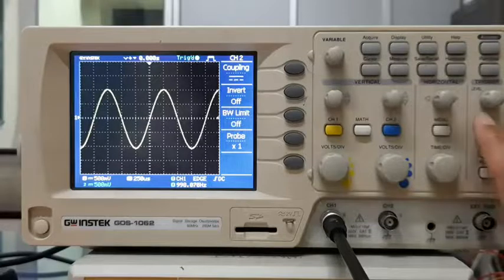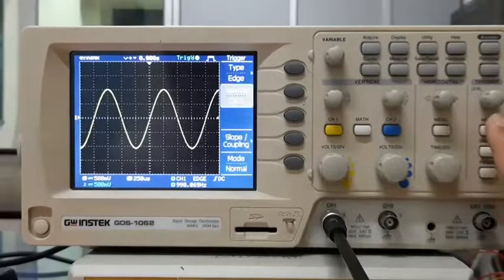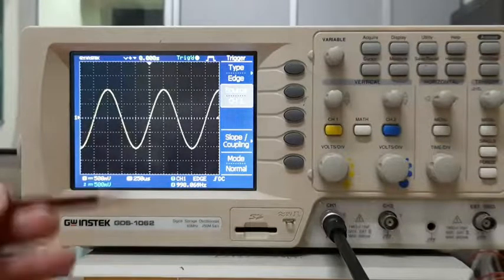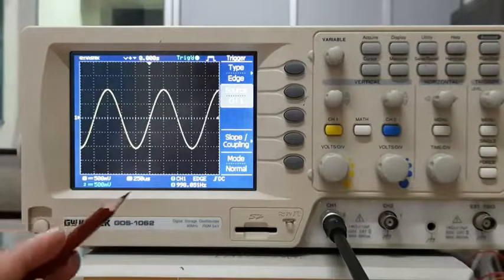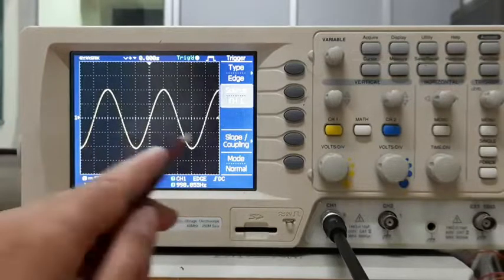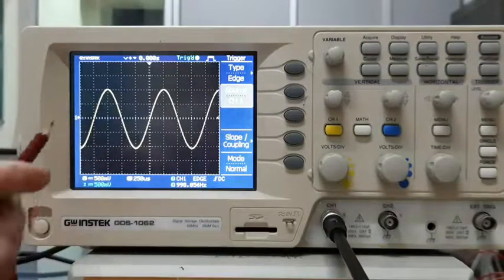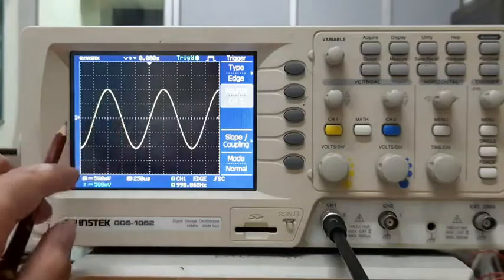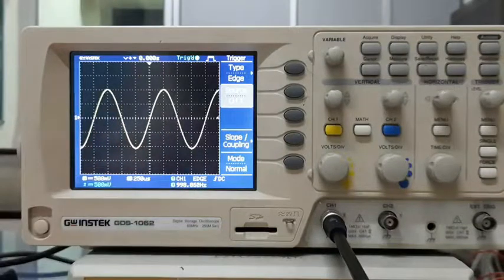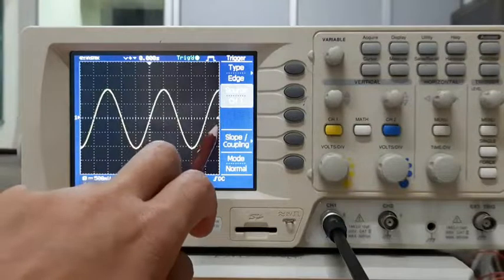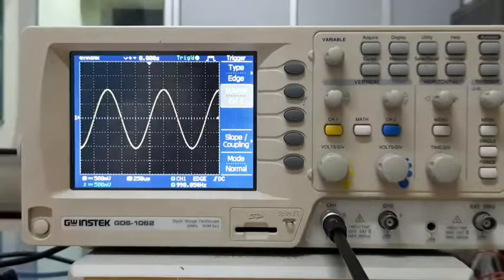Okay. Another important feature that one should keep in mind with this trigger is the trigger level, right? So this knob above the menu, the trigger level is basically when you move it, it will be shown somewhere here. So for example, on the left hand side with this 1 and that arrow, that shows the DC level, the reference level of your signal. So where the 0 is set, the right arrow, this small arrow here, shows what is the reference value, the voltage value at which the oscilloscope triggers.